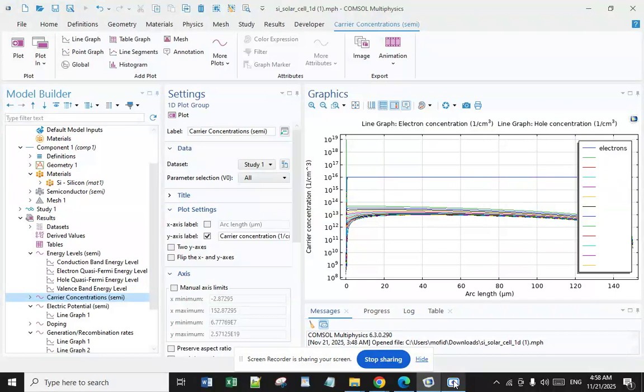We account for the main recombination effect with the Shockley-Read-Hall recombination model, implemented via the trap-assisted recombination feature. To simplify this model, we add an arbitrary user-defined expression to represent the generation rate with the user-defined generation feature. By doing so, we can avoid detailed modeling of the photovoltaic effect's carrier generation mechanism. It is also possible to add sophisticated expressions to make this model more advanced.